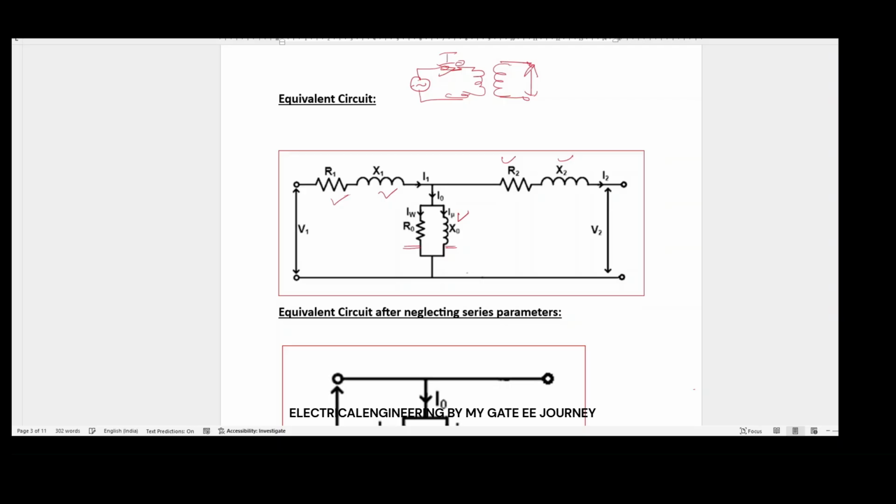What is that current, and for what purpose is that current being utilized? There are two purposes. One is it creates magnetic fields which link the secondary winding. To create the magnetic field, it uses the current. That is called magnetizing current, nothing but Im. In some books they refer to it as I mu.